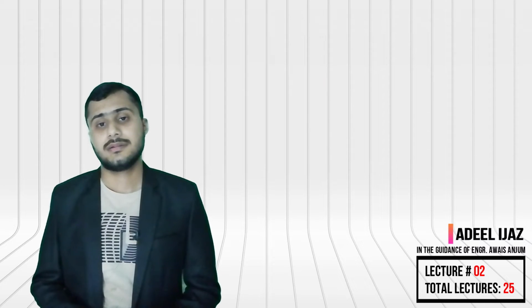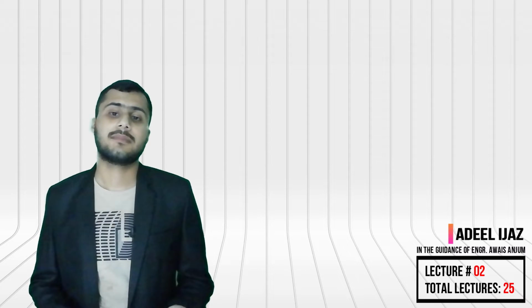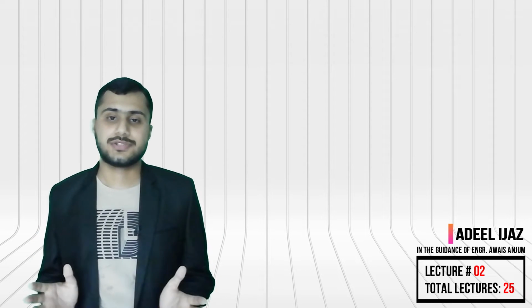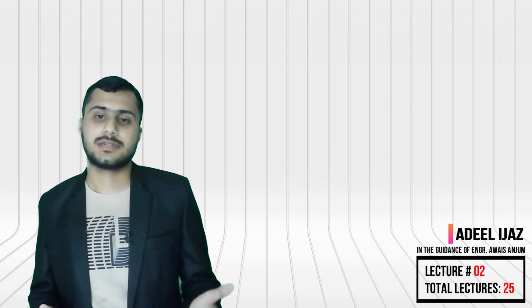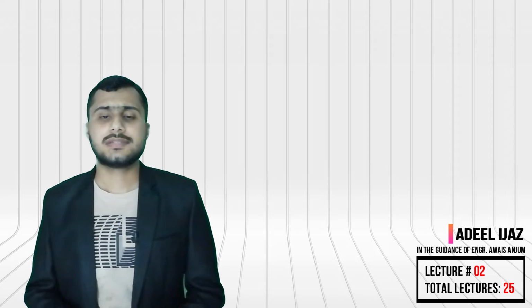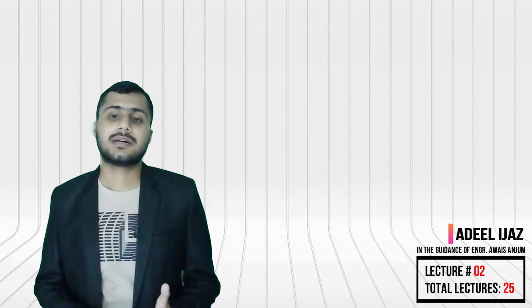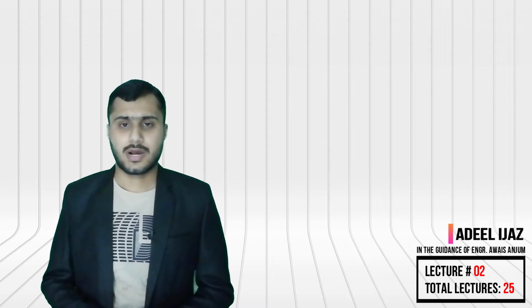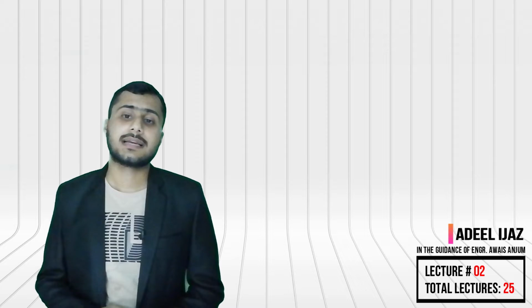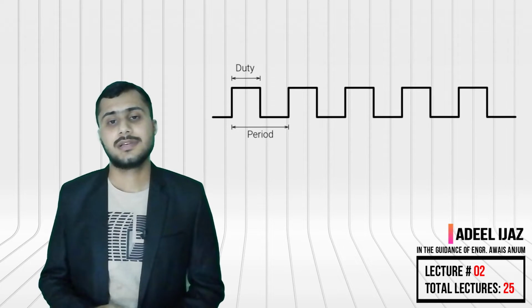On the other hand, there is a PLC with a transistor type. It can perform all types of operations of the relay type with some advantages of transistor type. Transistor type PLC have very little response time and we can run high-speed programs using this PLC. For high-speed program, we can take example of pulse width modulation, also known as PWM.